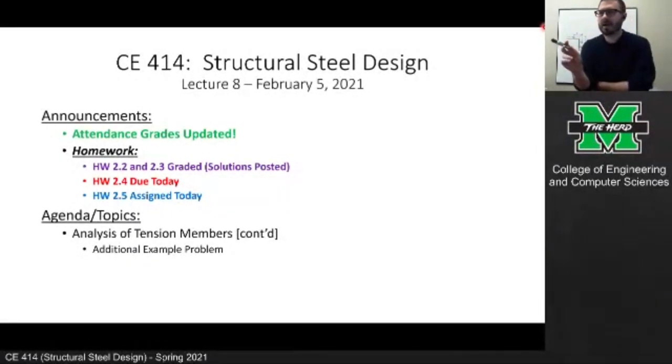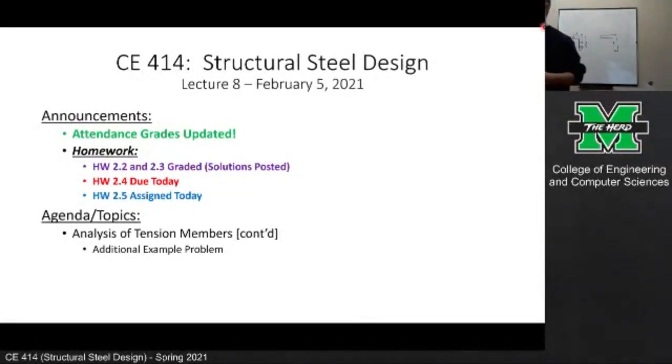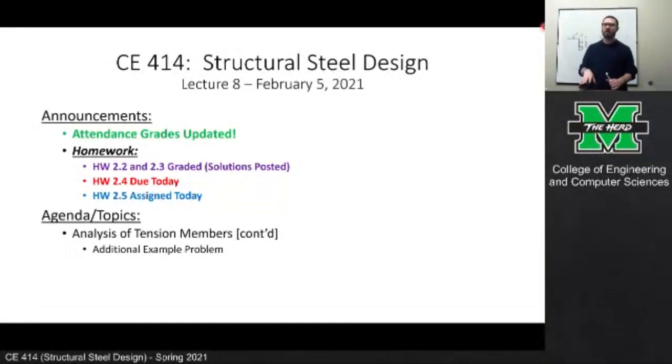So I'm going to turn that around to the class. Anybody know which one to use whenever you have a range? Always the lower one. You always use the lowest value. That's correct, because the reason that the range is presented is because certain grades of steel can actually have a range of FU values. The reason for the range is because higher strength means lower ductility. So you as an engineer need to be aware of that in some scenarios where ductility matters, like in earthquake land. But in general, whenever you have a range, use the lowest.